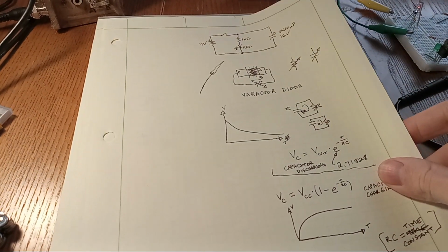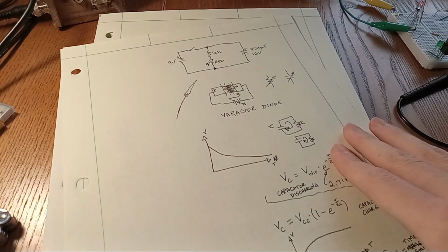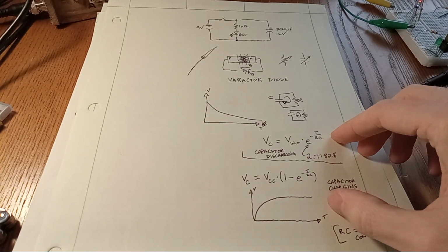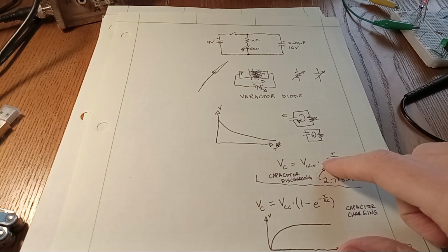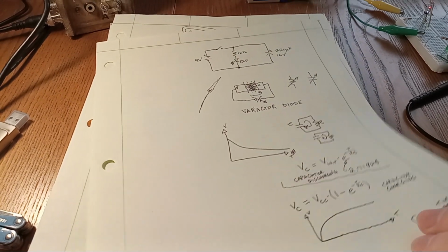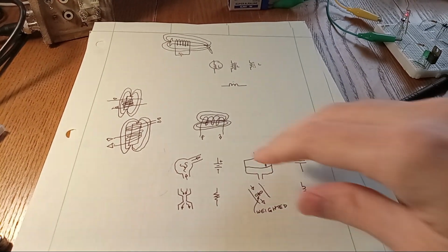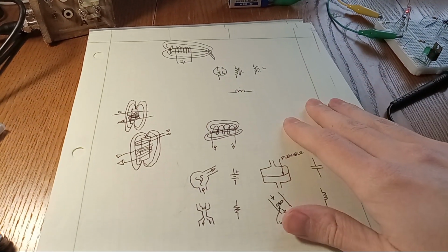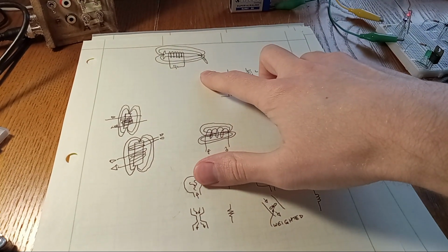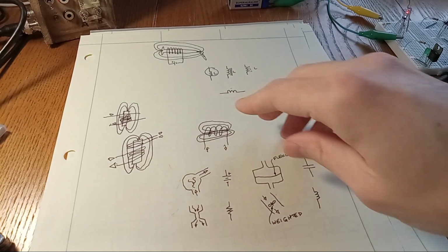Talked about capacitors more, how you could use a diode as a capacitor, and gave equations for capacitor charging and discharging. There are equations like this for an inductor, but they don't come up as often, so I glossed over them in my description of inductors, which are basically electromagnets. Wrap 2 of them around the same core, you get a transformer.